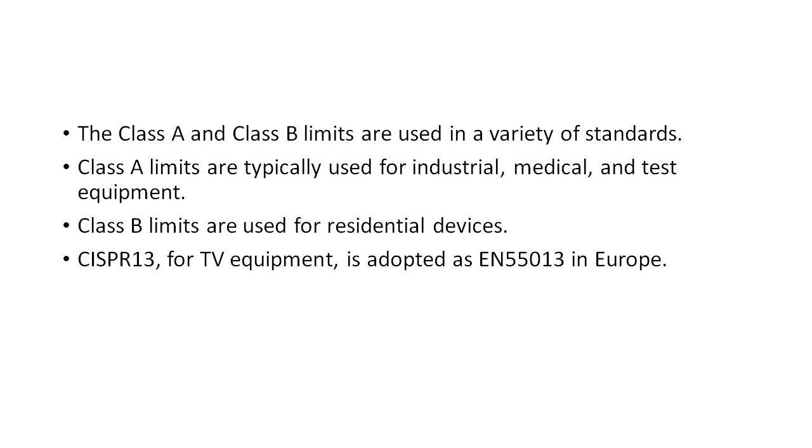EN 55013 is for the sound and television receiver equipment family, and though it measures several types of emissions associated with those specific characteristics, unintentional, conducted and radiated emissions that aren't directly associated with things like channel carrier frequencies must still comply with the Class B CISPR 22 emissions limits. This is analogous to the FCC requiring that things like cell phones have their transmitters be subject to specific rules, but then having them turned off and requiring the phone's electronics to be tested to the Part 15 EMC rules.